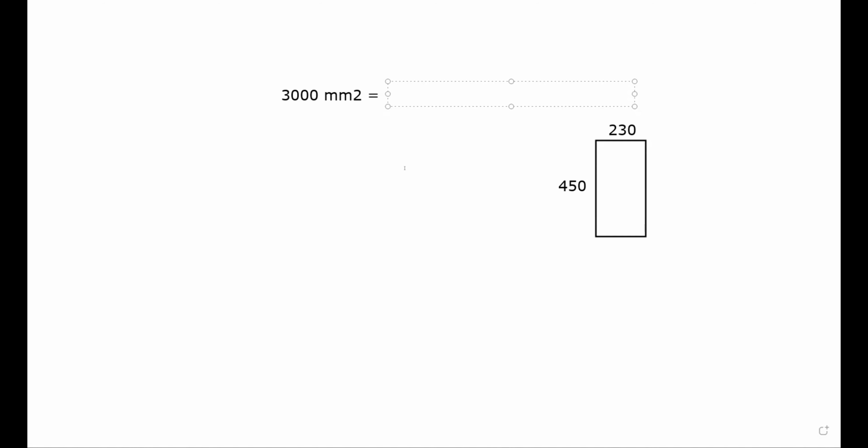25 mm dia rods. So first you should start with 25 mm dia rods. Minimum 10 is there, but 12 for columns is preferable. For beams, you can go with 10 or 12, but 12 is suggestible. 10 dia rods and 8 dia rods we'll use maximum for stirrups. We will not use them for load carrying purpose, but only to bind the main rods. We are going to use 10 dia and 8 dia as binding materials. But preferably 12 is better. Maximum go with the 12 dia rods. For stirrups, 8 or 10 we can do.